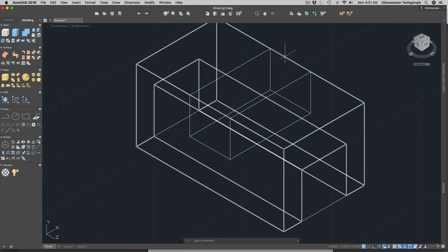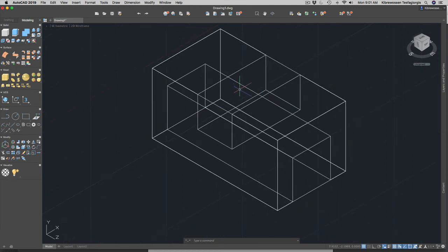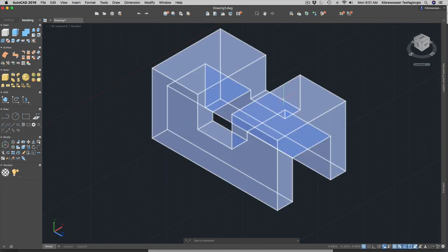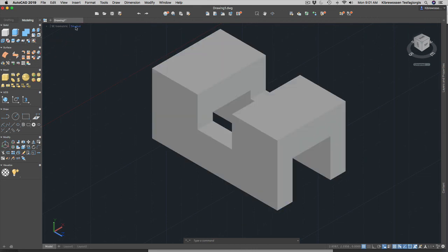So I have two objects. If I use the intersect function between those two, then I can generate one unit, right? So therefore, intersect. Okay. Then I'm going to press 1, then select the other one, two of them, and then press enter. That's it. So I just created my three-dimensional drawing using the intersect function. Nicely done.